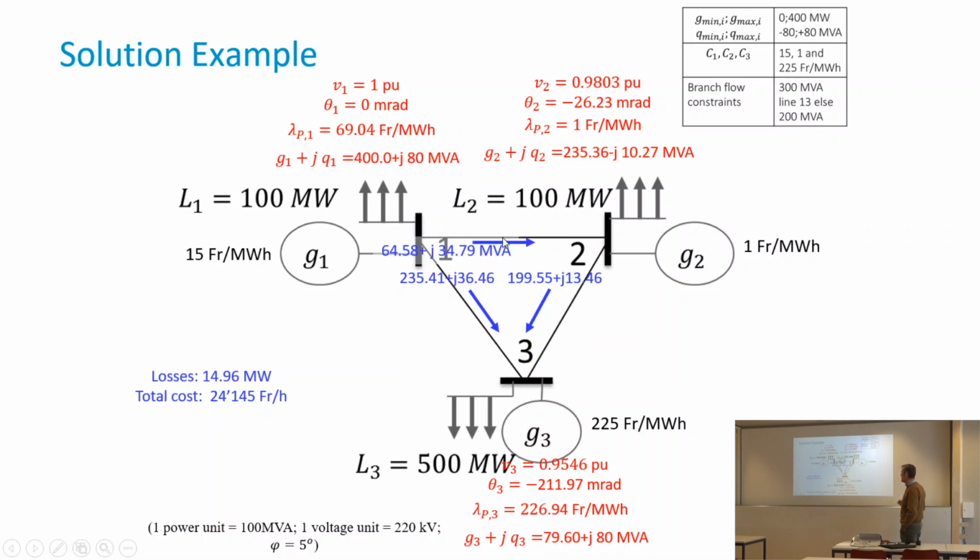The reactive power also has an impact on the voltage. Typically, we see that reactive power flows in the direction of decreasing voltage, which we see here. Here the voltage is 1. There is a positive reactive power in this direction, which means voltage at bus 2 will be less, and at bus 3 it will also be less. So if we have a voltage problem in a grid, we may also, by playing with the reactive power, change the voltage in the nodes.